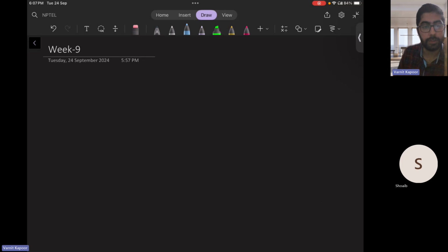Again, if you have, say, a non-Newtonian model for your viscosity, then also we would need gradients of the velocity, because the gradients of velocity are required in the non-Newtonian coefficients that need to be calculated. So as a result, we need to calculate the gradients of velocity. Similarly, if you are solving for turbulent flows also. Let me write first this much. Gradient calculation.